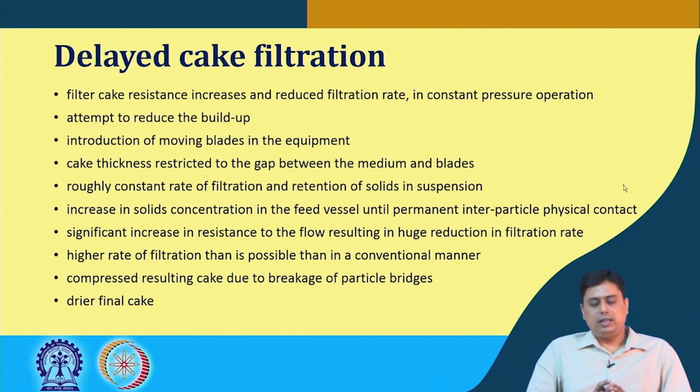And since these suspensions are getting more and more concentrated, and we have this cake of a controlled thickness, we can have a drier final cake in such a case. It is becoming compressed, and since it is becoming compressed, the filtrate that was there loosely inside the pores is becoming more and more drier.